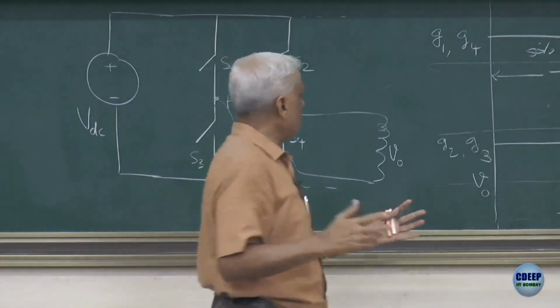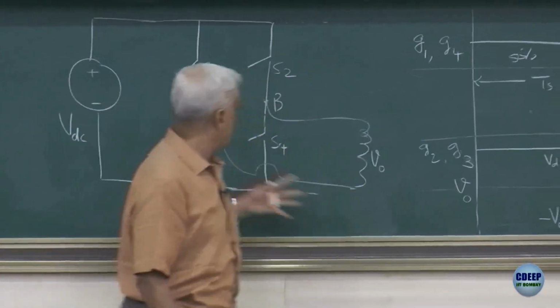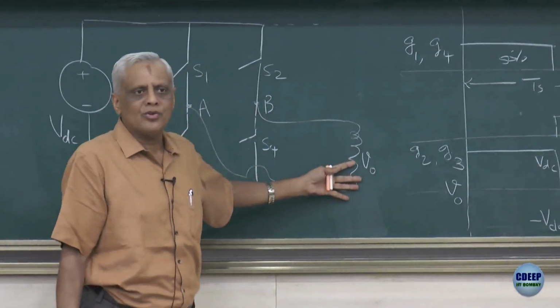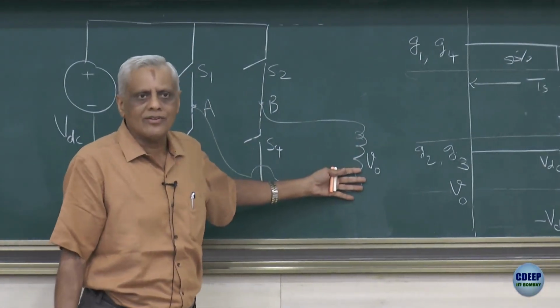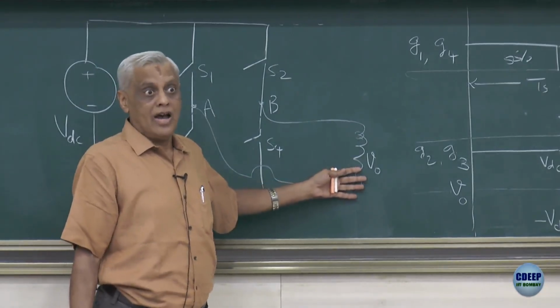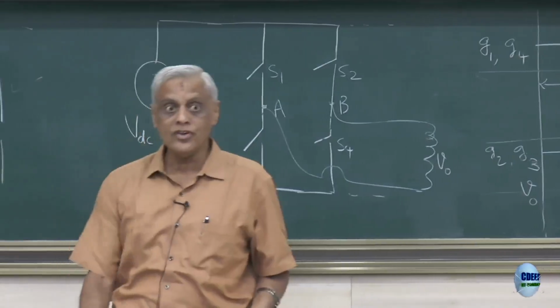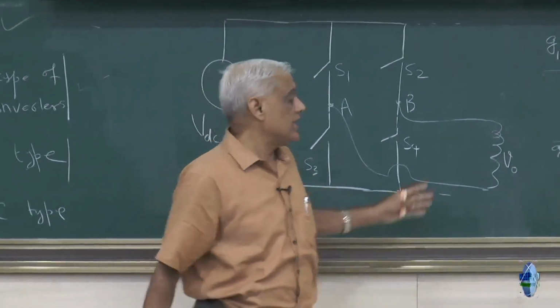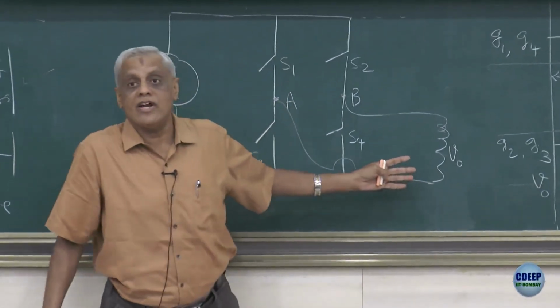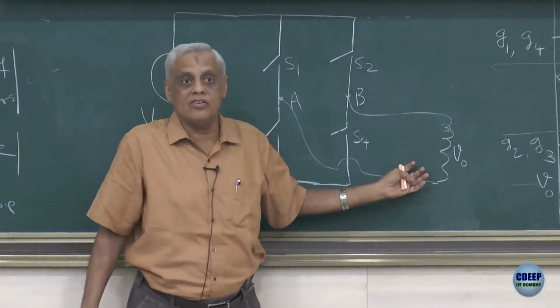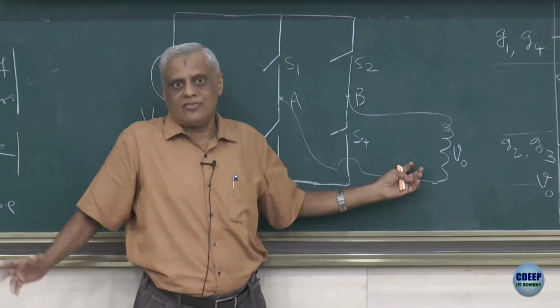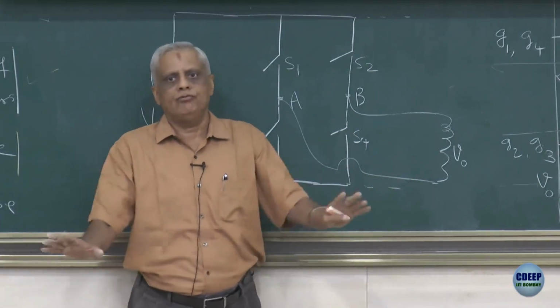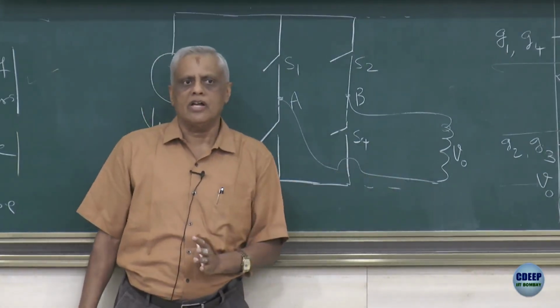So if you are applying this kind of a waveform, a lot of harmonics are also going into the stator windings. Now if your machine is very expensive and very sophisticated, you cannot let that happen, because it will wear off the windings, insulation and so many things, will cause heating and other things. The machine life will be reduced.